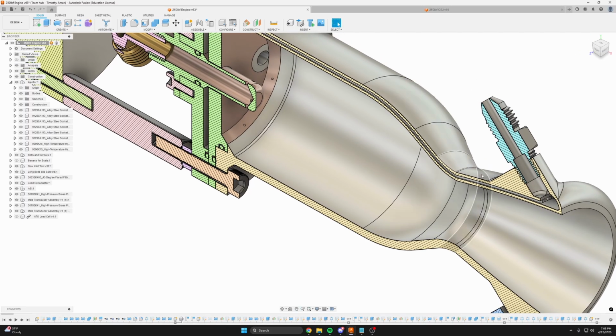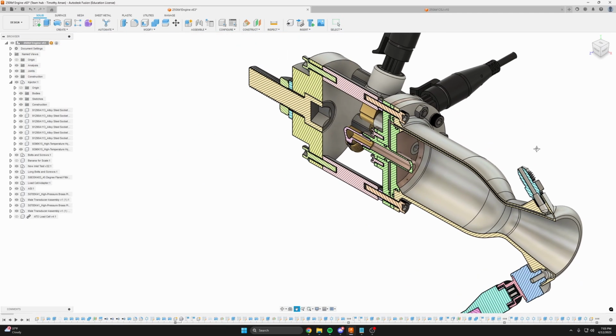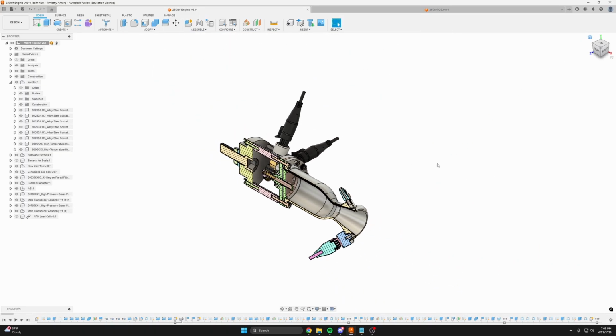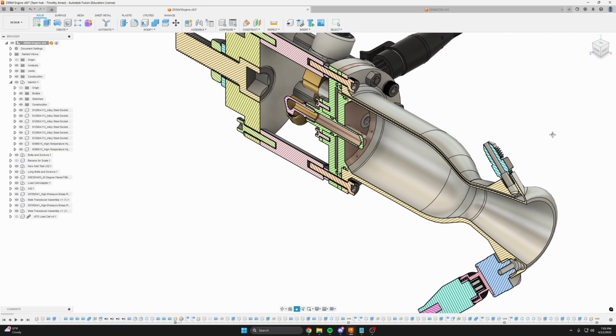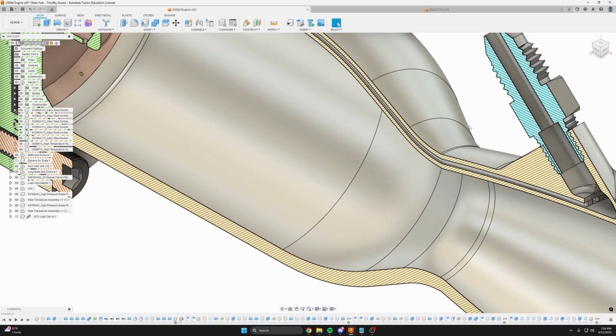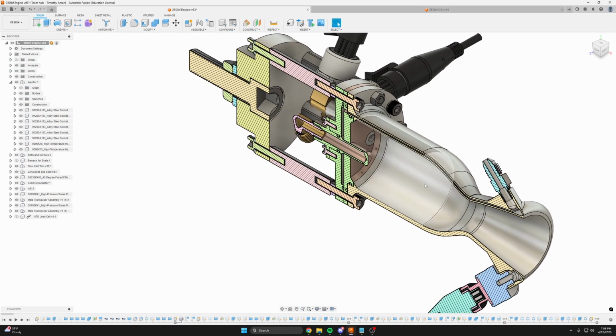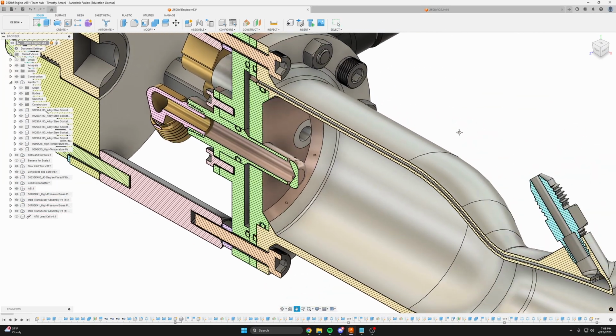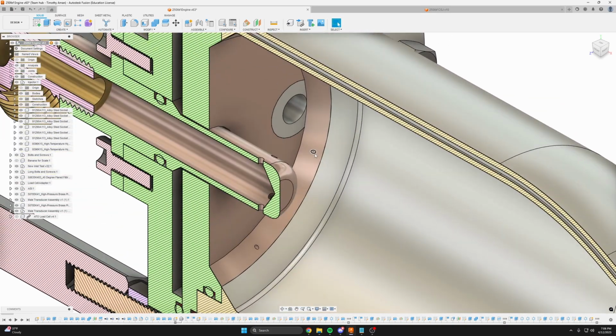So for the AlSi10Mg, I would recommend trying to stay under 600 Kelvin, or under about 300 C, if that's the material you're printing in, because your yield strength really drops off a cliff after that. But you have to do your own analysis. If your throat is really small, the hoop stress is not so bad, and maybe you can get away with a higher temperature than that. Those all go hand in hand, and that will decide whether you need film cooling or not.